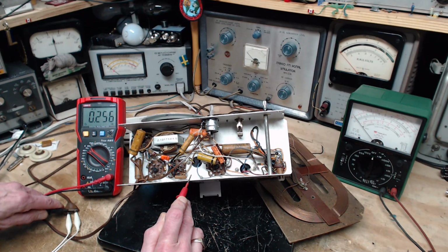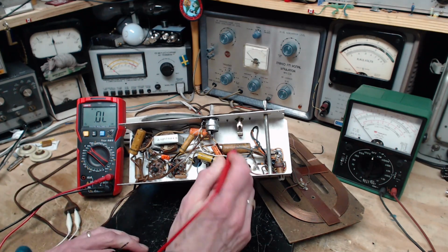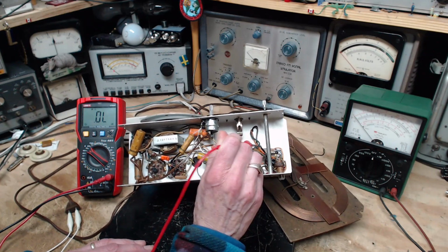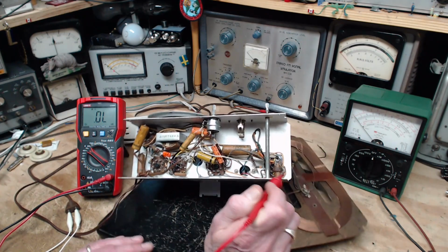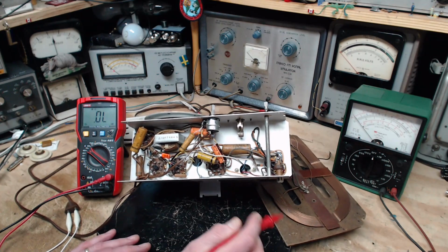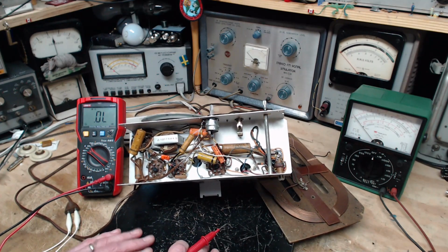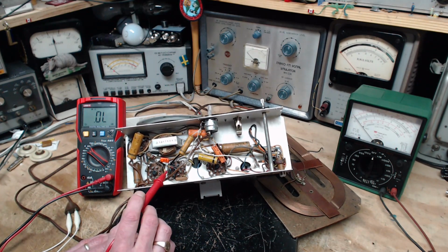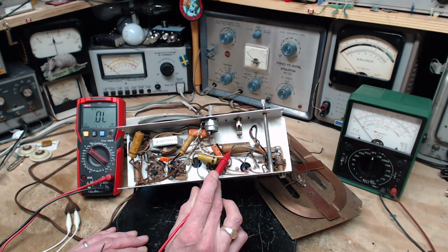227, 220. So that's the resistor, which we haven't found yet. Somewhere there's a 220 resistor also connected to the chassis. Where are you in here? So 220 would be a red. Yeah, look, here's a 220 right here. Red. And how does this end up being in parallel with that?